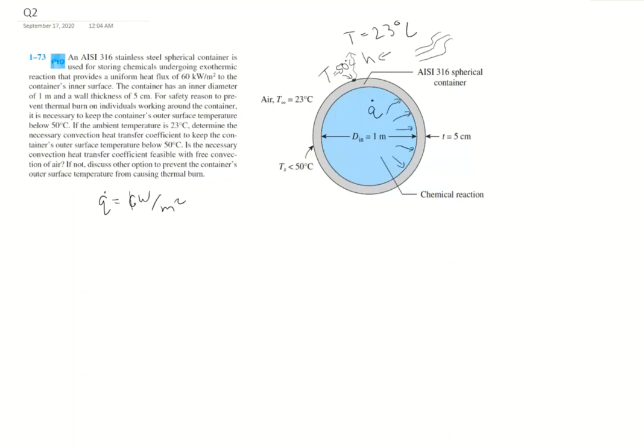And so the general convection, which you've seen, is equal to hA, and then usually we'll say T surface minus T infinity. And infinity is just far enough away from the pipe that you've reached ambient conditions, because right here, for example, it's still going to be hotter than out here. So it's just when you reach this farther point. Okay, all that said,